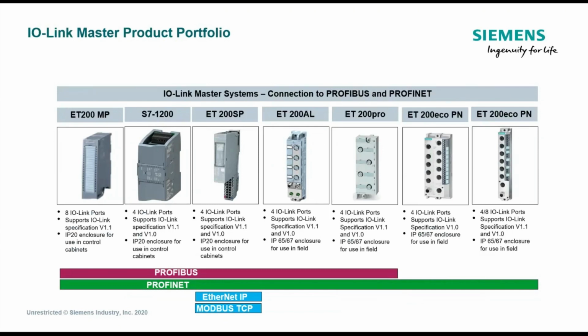Per master, it depends on the master. On a lot of our in-cabinet masters, say for the 1200 or for the SP, those support what we call ports or devices, 4 ports or 4 devices. But again, in our work, it's mostly devices that would give you analog feedback. But say our motor starters, our compact starters, and traditional starters, we can gang up 4 devices and make it look like one, or 4 starters and make it up to as one master.